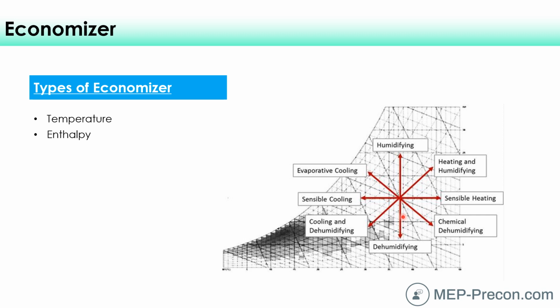So you could have low temperature and high moisture, or the opposite, and it could be around the same enthalpy. And so the significance of that is, if you just had an economizer set for, okay, once it gets to be, say, 55 degrees outside, we're going to bring in outside air. Well, you may not want to do that if it's raining out and it's 98% humidity or something, just because that's going to make your indoor environment really humid, and then eventually you're going to have to run your air conditioner to wring out all that moisture, and that's going to be expensive.